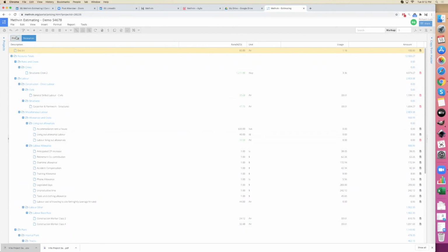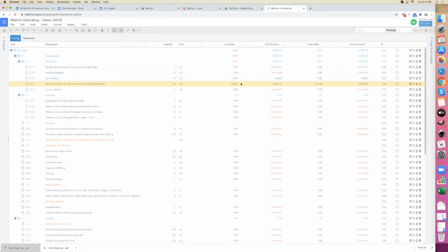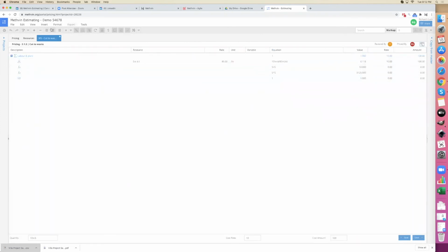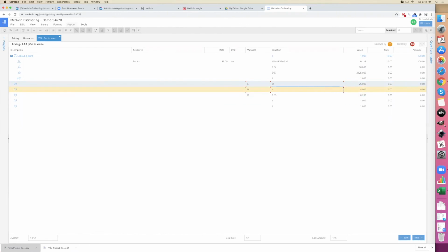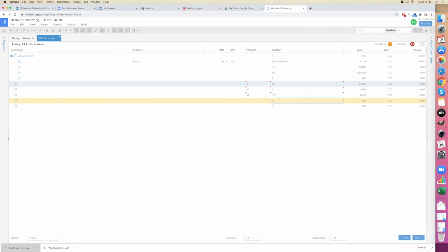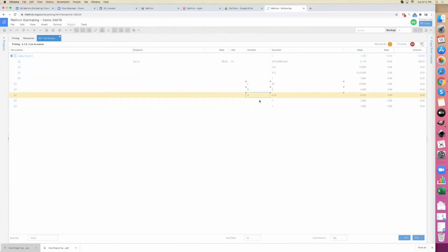Yeah, so I lost my train of thought, sorry. If we jump back into this line item that we're pricing, let me try and explain the variables a little bit better, make it a little bit more simplistic. If we go here and go length, breadth, and depth, you can give them values of 25, 4, and 0.25. If we want to determine that volume, what this actually is, is a basic programming language. It runs through a macro all the time, and you have to have set the variables first, and then you can use these variables in the equation after. It always has to be after.